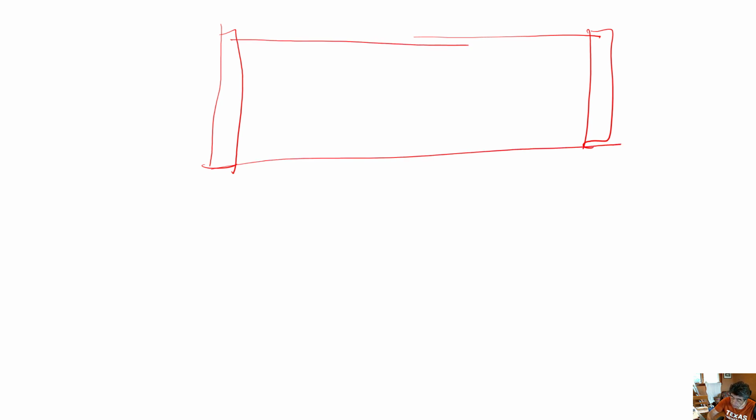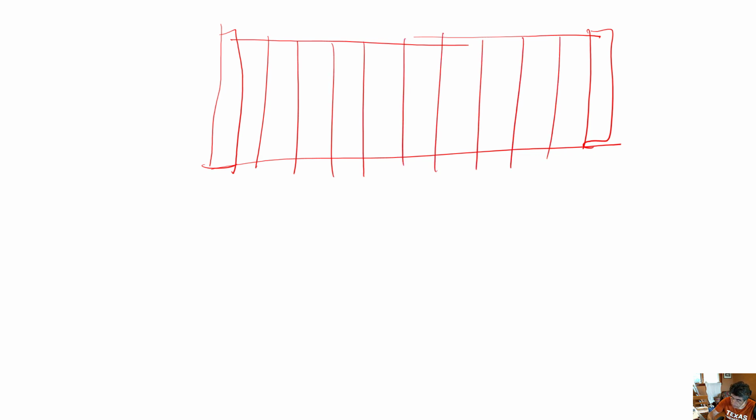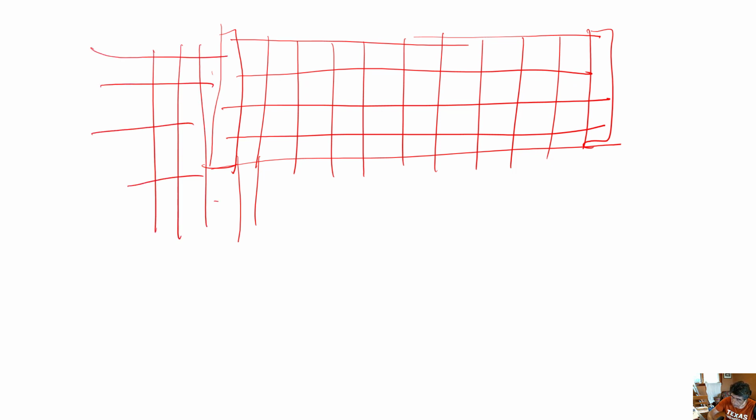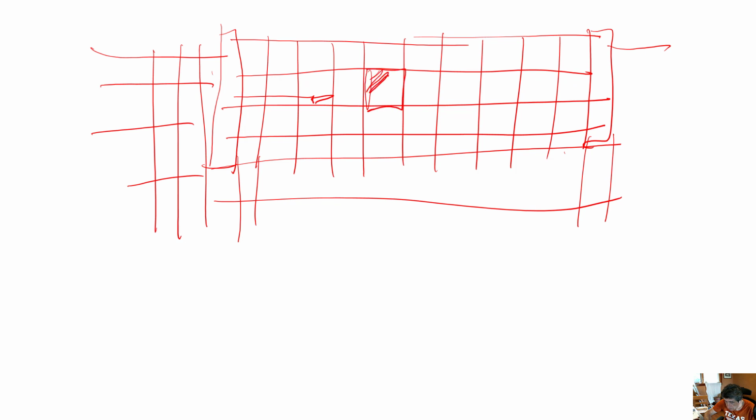And when you do this on a computer, you pixelize everything in between so that you can propagate the flow conditions. You can perform the fluid transfer on the computer. Of course, I'm defining this in a very rudimentary way over here. But what I want to point out is this: when you do this analysis of how fluids move in the rocks between two wells, you don't have the luxury of having too many cells to have superfine detail in the cells, because that will entail a lot of computer memory and also a lot of CPU time to do that.